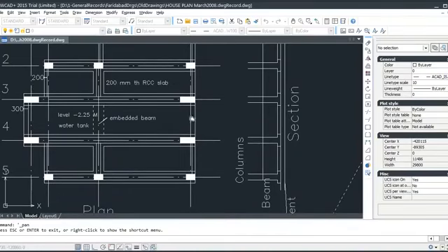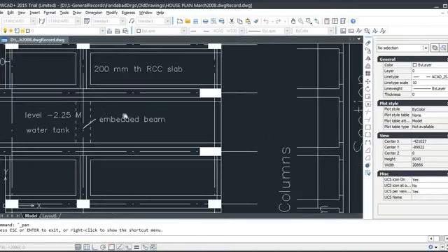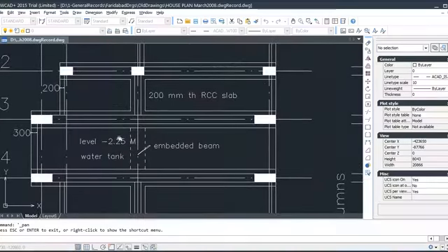This column and this column are about 37 or 36 feet, or 11 to 12 meters apart. Here you can see, here is a column, here is a column. This is less, this is very long, and because it is a hall, we wanted this portion to be full height, treble height, about 7 meters or 6 meters. We do not want a column here. If we fix a column here, then this can't be a hall, it will be like a room. So we just did not put any column.